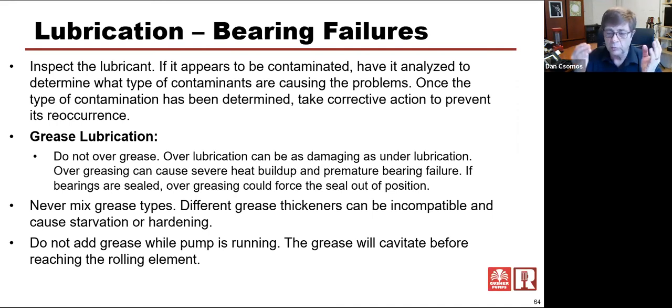They're shorthanded, everybody's leaned out. So running a bearing without oil, if it's an oil bath bearing, is really a bad thing. And again, on that bearing rotation, you only want it to splash in the bottom. There's only a little bit of oil level change between completely dry and having the right amount of oil. If it loses some oil somewhere and gets down below that, you're running that bearing dry, and it's going to fail quick.